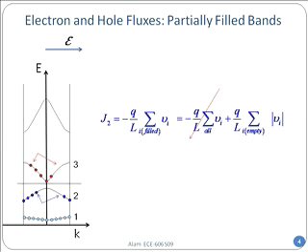Because then you see there are millions of them, so I don't sum them all. There are few empty states. I focus on them. I assign a plus q charge. Look at that: I have, instead of a minus q over L, a plus q over L left. So I assign a plus charge and let the holes move, in this case the empty spaces, in the same direction as the electron, with plus velocity.